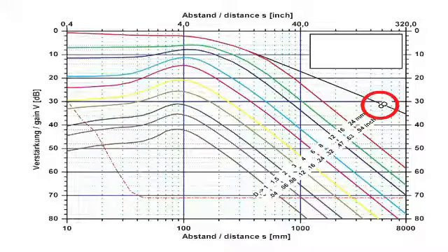For example, a real discontinuity might be stated to have an equivalent reflector size equal to a 3 mm diameter flat bottom hole. The DGS diagram therefore exactly describes the distance laws, which depend solely on the shape of the sound beam and the reflectors.